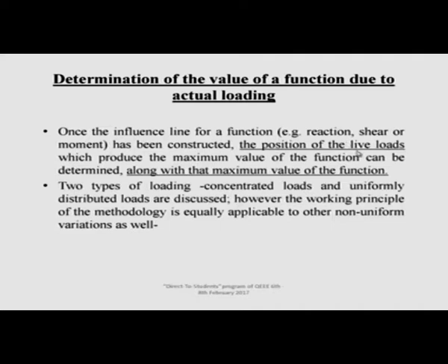And there are also internal stress resultants, shear and moment, and the position of the live loads which produce the maximum value of the function can be determined along with that maximum value itself. That means you are determining two things: one is where that function is becoming maximum, and also what is the maximum value of the function.